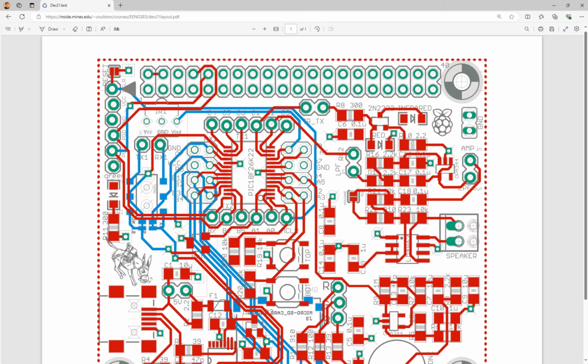However, if you want to verify that, for example, directly feed that electrical pulse, the digital signal, to the LED, it should turn on, right? Should turn it on. However, the receiver is not receiving anything. So in that case, you can use a camera, turn off the light, and look at it, see if the LED is really blinking under the camera to check if the LED is dead or not. But what you can also do is just swap the board, replace it with a different board, and see if that works. Just telling you the different ways to verify the functionality of the board.